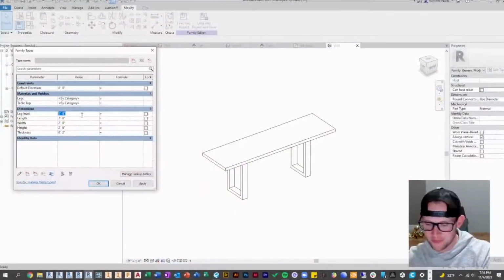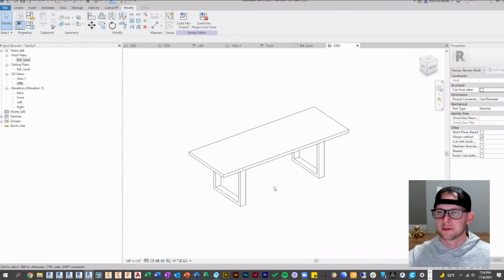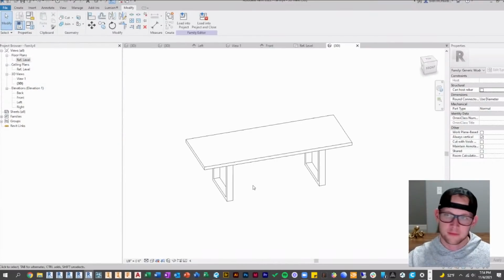Right. And actually what you just did there, going back to the whole creating types to flex, one of the nice things about what you're doing is you can apply one parameter at a time too, right? If you did a type parameter, you'd be flipping them wholesale. And if you needed to troubleshoot, it may be helpful to say, change this first, click apply, change that, click apply. So I guess that's two approaches to flexing our skeleton.